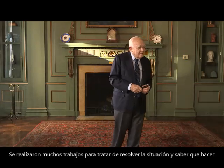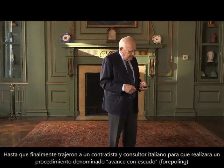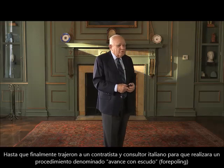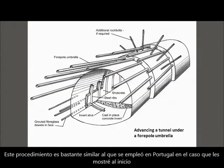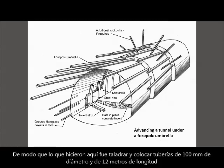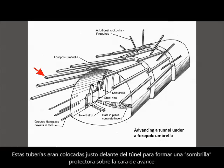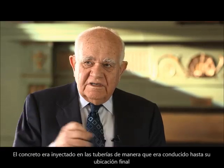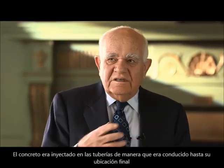A lot of work went into that to try and figure out what to do, and finally they brought in an Italian contractor and consultant to do a process called forepoling. And this is rather similar to the earlier example I showed you in Portugal, but in this case the rock is so bad and it's clay-rich, so you can't flush it easily. It's too sticky, and so what they do here is drill in pipes, basically 12 meters long and about 100 millimeters in diameter, and these are drilled right ahead of the tunnel to form an umbrella over the face, and the concrete is injected into the pipes so that they are grouted into place.